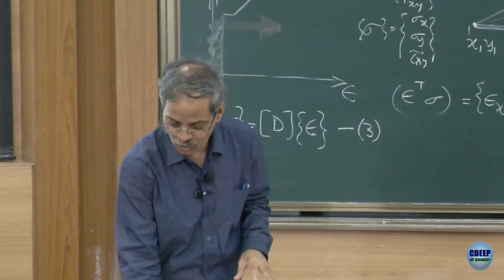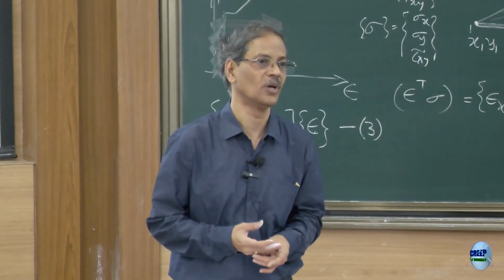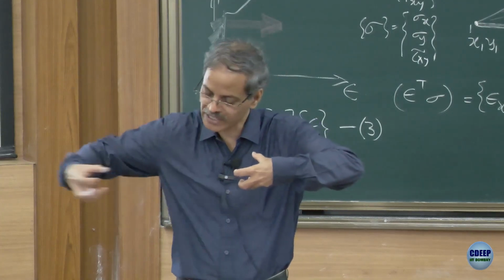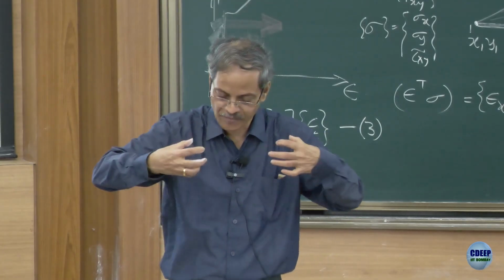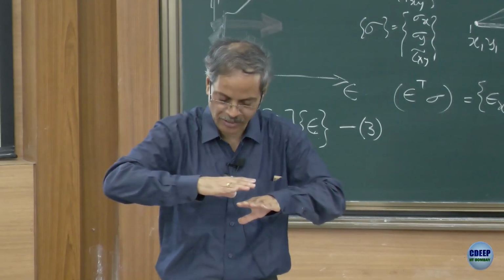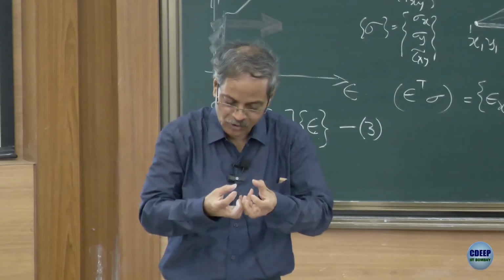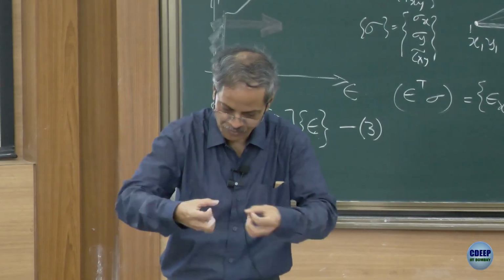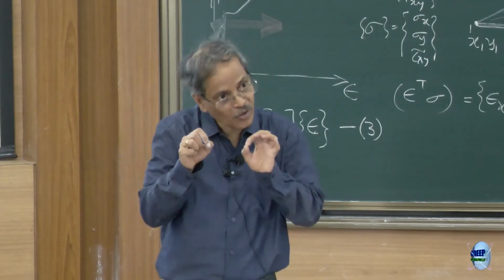The external forces could be like you have seen in yesterday's class while solving a tutorial problem. At any point, the force can be in 2 dimensions: along the x axis, along the y axis. Correspondingly, you have to calculate the work done by the forces, the potential of external forces, due to forces that are distributed over the element, and there could also be concentrated forces.